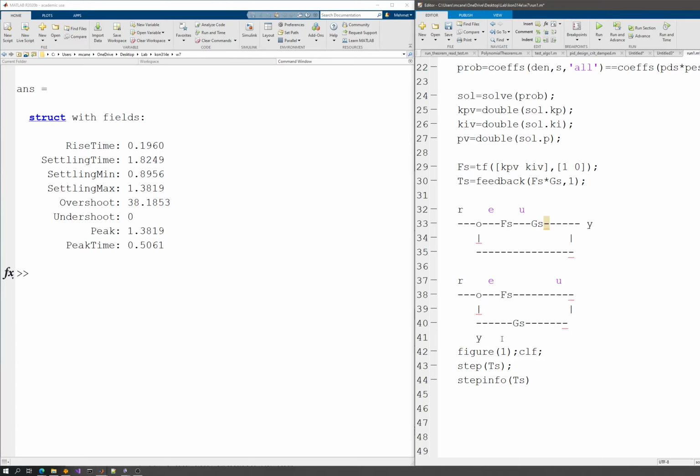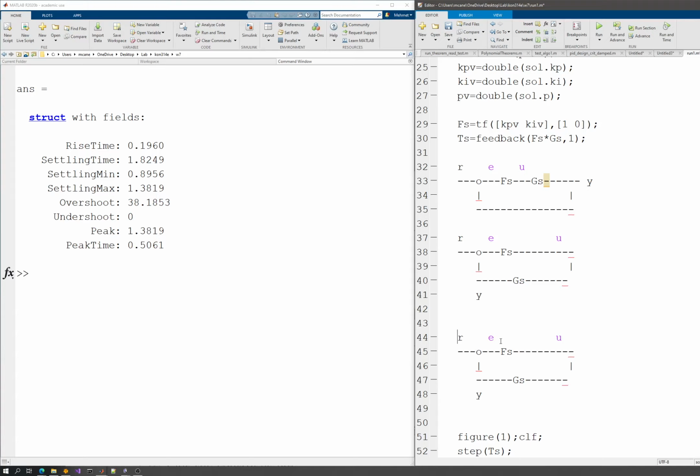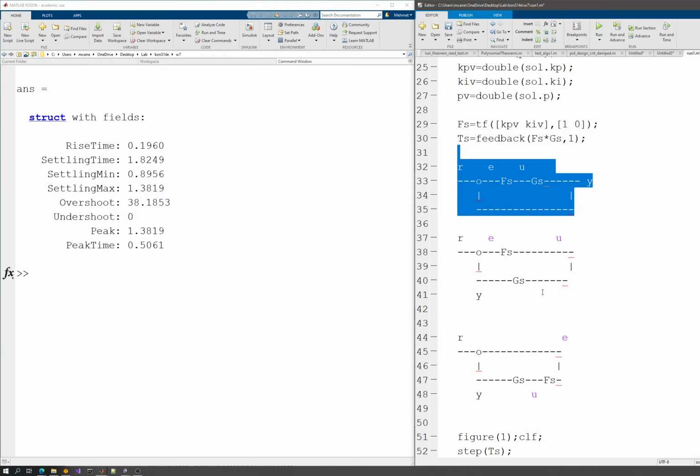Now there's another version where I might also be interested in the error signal here, which might be the case. So this time this goes into the feedback path, so I'm taking it away. This becomes the output, and somewhere here should be F(s), because now I am feeding back, sorry, I'm feeding back my error. So my error should be applied to the controller. The controller should give me the control input, the input of the system, the controller output. That should be applied to the system, and then the system should give me Y, and then I have R minus Y, which gives E. So these three connections are very essential, and if you know these, you are a little bit more aware of the error, the control effort or signal, and also the output. We're used to this one, but these may be new for you.